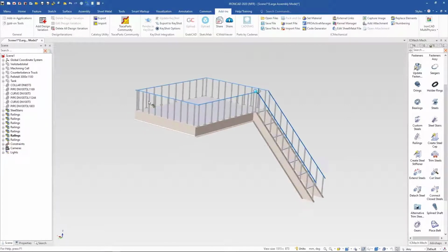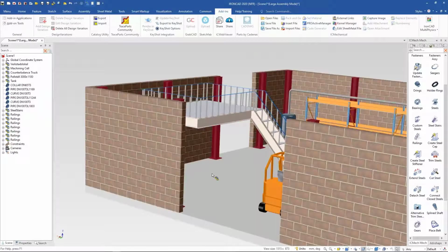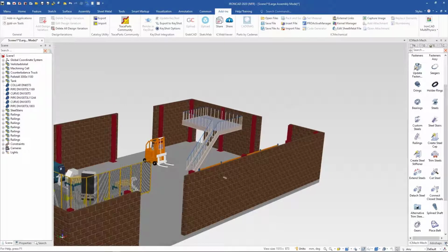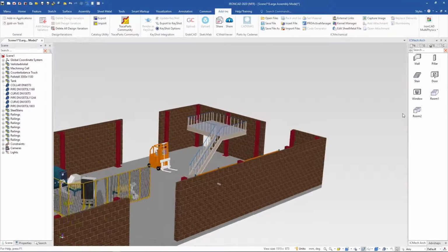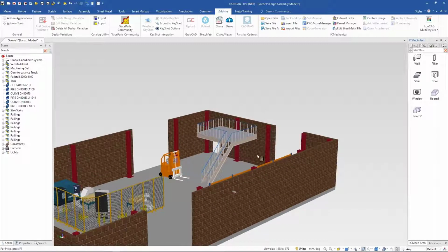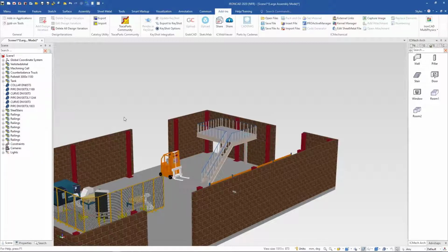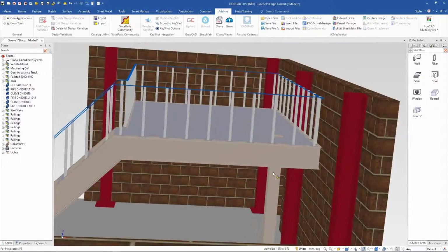All right, let's look at that. So we created our railing system. Bring back everything else, show all. Well, we have another library over here. We have an actual architectural library where all I would need to do is bring in a pillar. Put a pillar right here. It's a rectangular pillar, 200 by 200, 3 high. And no problem, I can change it later. Just say go ahead.